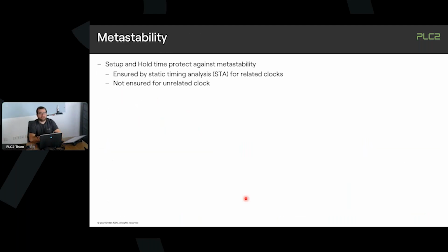Okay, so let's understand some basics in the background. What is metastability and what's going on here? Usually we have flip-flops and there's a defined setup and hold time. And this is our safety boundary around the rising or falling edge of a clock when a flip-flop is working to protect the input of a flip-flop from metastability. So when you're not violating setup and hold times, everything is okay. And tools like Vivado have the static timing analysis called STA, which is taking care of this, computing your delays inside and checking if signal changes are done before the setup time is violated.